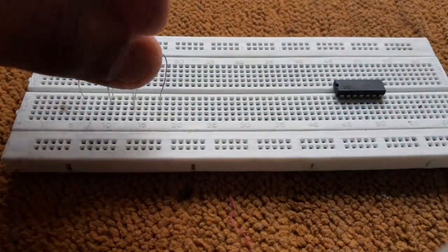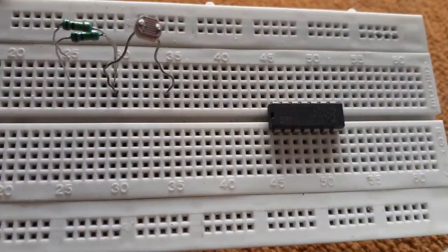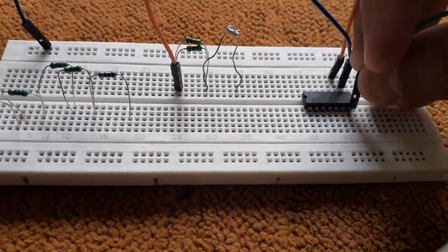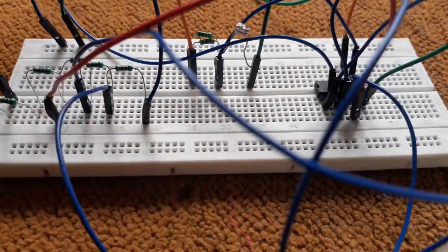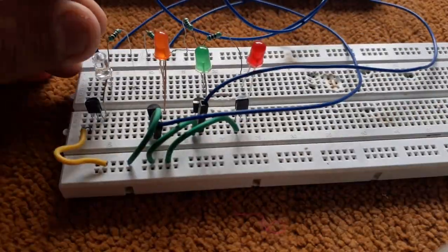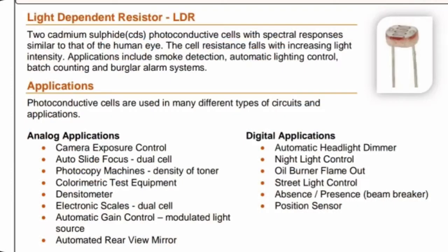Then after the theory was out of the way, I started creating it practically on a piece of breadboard by first fixing the voltage dividers, then the ICs, and finally the LEDs and the transistors which would switch the LEDs according to the command of the IC.